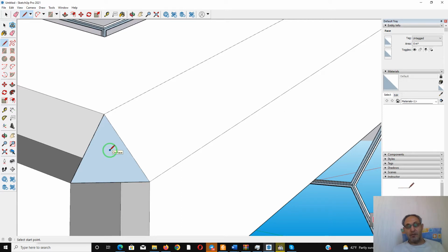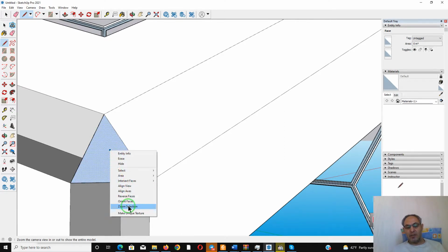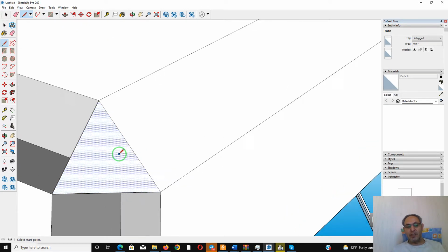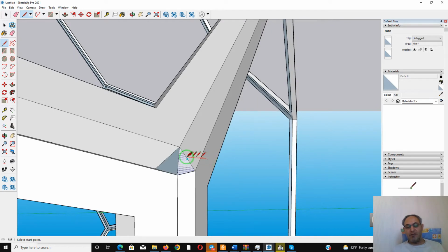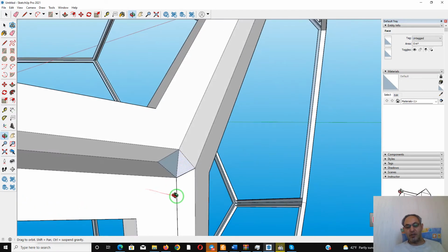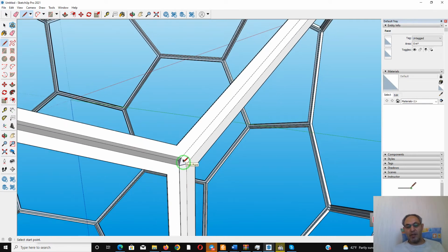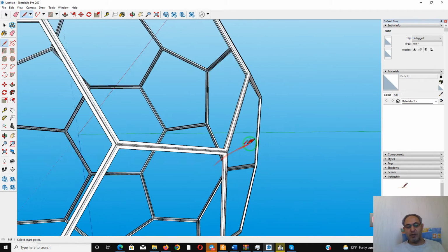And if you want to fix this problem, we can right click and then orient faces or reverse face, so that this becomes like reversing the face. If you press orient faces, it may make problems. I'll do it and check whether it's possible or not.